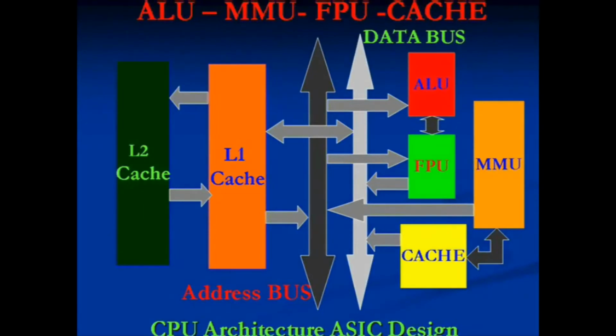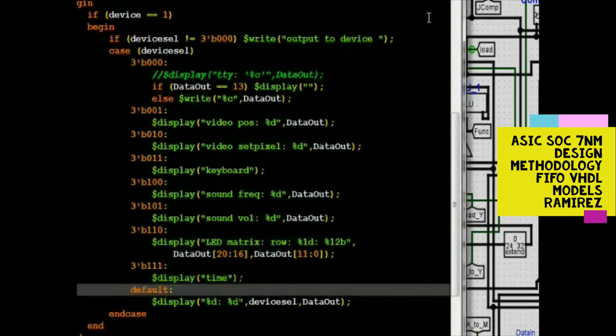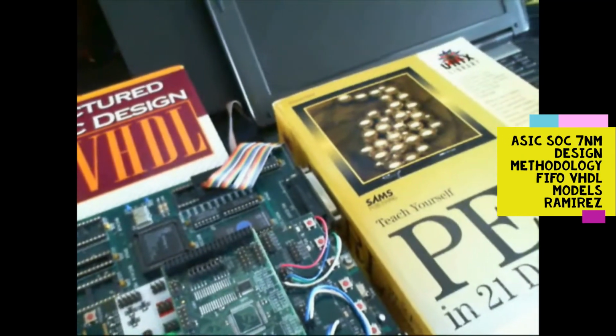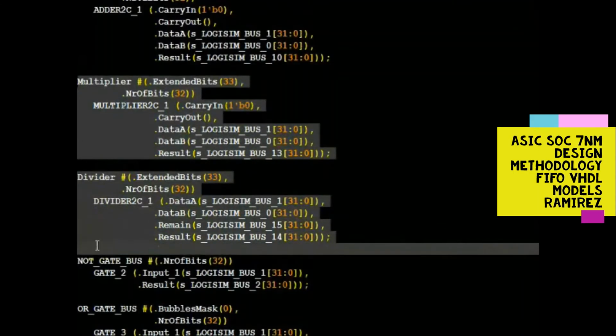The functional specification of the design is done. The HDL coding in VHDL and Verilog RTL. The RTL behavioral or functional simulation of the VHDL code. The logic synthesis, followed by test insertion and ATPG. Then the post-synthesis or gate level simulation, and finally floor planning and place and route.